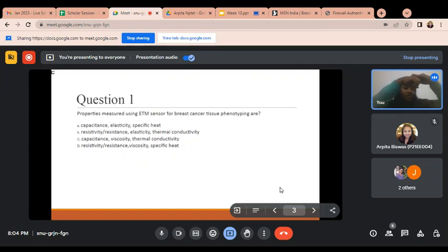If we dip this wafer into the etchant solution, taking TMAH as an example, the silicon is dipped into this TMAH solution. If a mask or oxide is present, it will etch in a particular direction, so it is anisotropically etched.